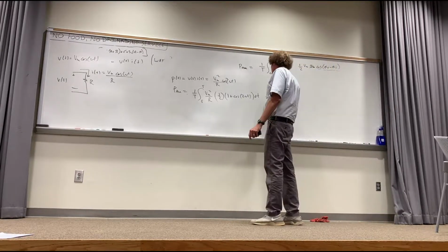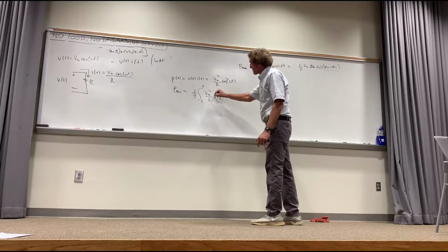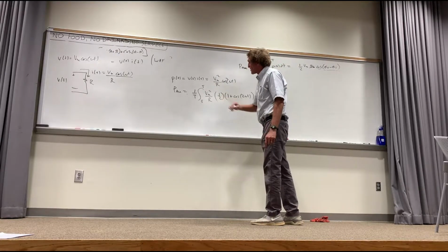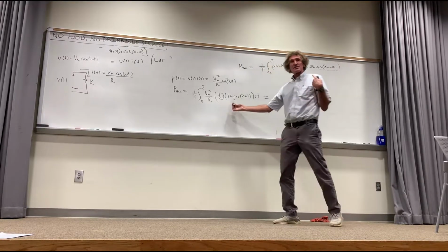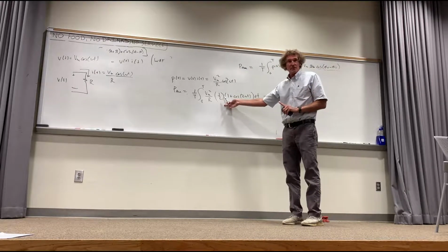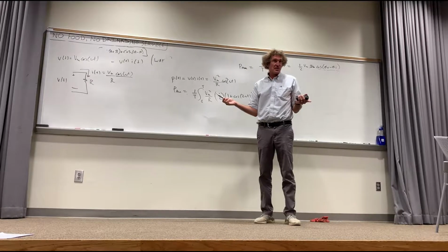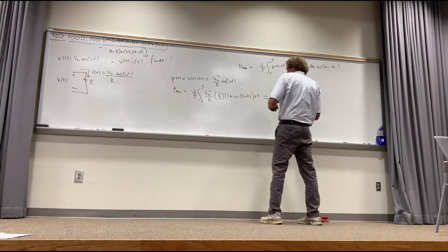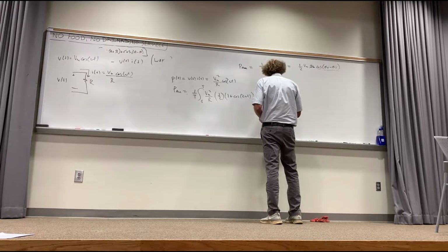Now, what do you notice happens here? What happens to 1 dt times 1/2 Vm squared integrated from 0 to T, with 1 over T in front of it? You all see that's just going to bring out a constant. If you integrate a constant from 0 to T, you get T, right? Then if you divide by T, you just get the constant. You all see that, class? Here, you're only going to get 1/2 Vm, that's magnitude squared, over the resistance.